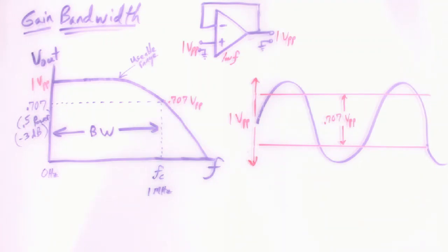And if you don't have offset, you can use peak measurements. It's fine if you have a preference, but just be watching out for things like offset that can throw you off. I should mention in your Analog Discovery, if you have a lot of offset present, it might be worth looking at the calibration routine. I think I remember seeing one.